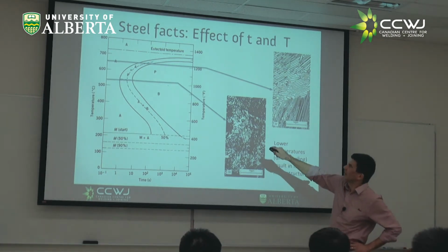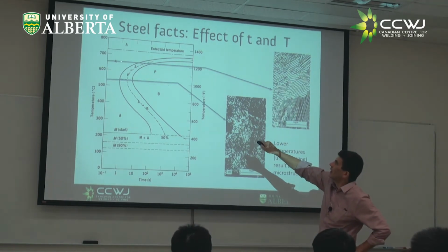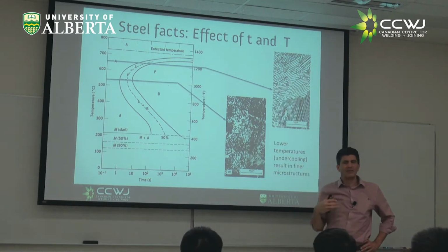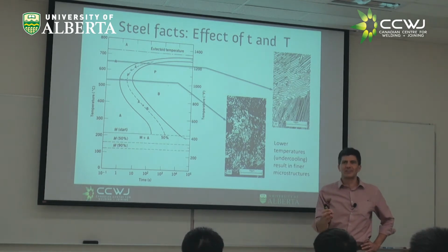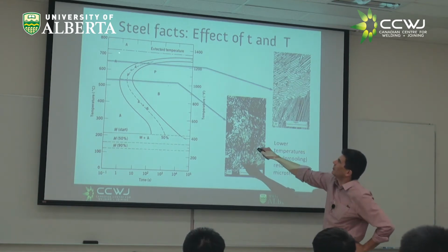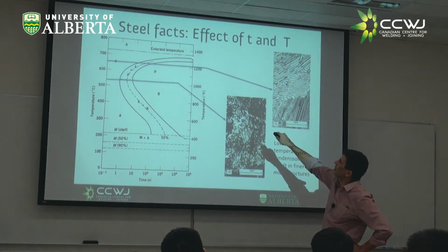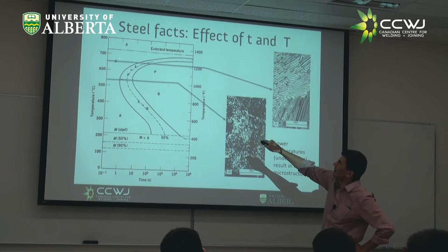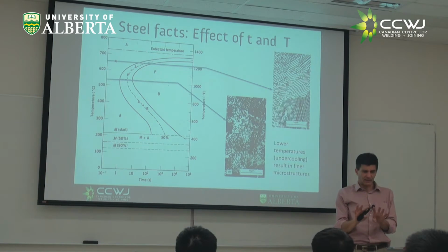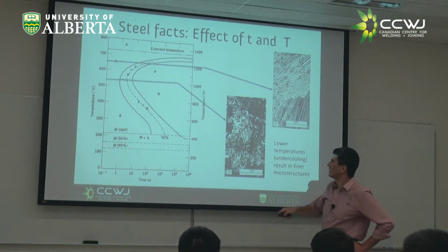It's quite significant. And what we see in this curve, some people call it a C curve, right, is that if I'm close, this is the eutectoid temperature, the 727. And I pick this steel that nobody wants to weld. I'm telling you, crazy experiment on a crazy material. But the explanation is the easiest. So if I'm above here, nothing is ever going to happen. If I'm just below, it's going to take very, very long. And as I get down to it, right combination of driving force and diffusion, it can be very fast. And then it starts to get slower, slower, slower again.